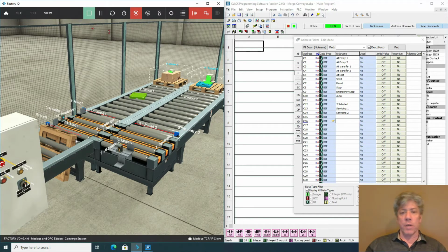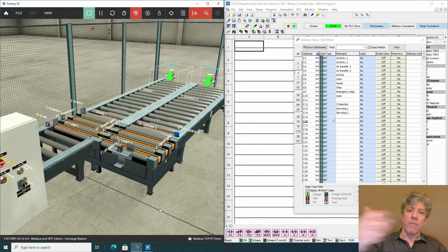So I'm going to show you something called finish flags. Now, usually a finish flag is more used when a whole process is finished, but it's also correct to say you could use a finish flag to remember that events have occurred. And really, you've used finish flags in a sense, because the seal-in circuit that I've already taught you is a circuit that remembers things, right? I mean, that's what it is.